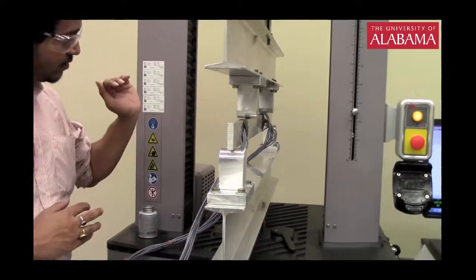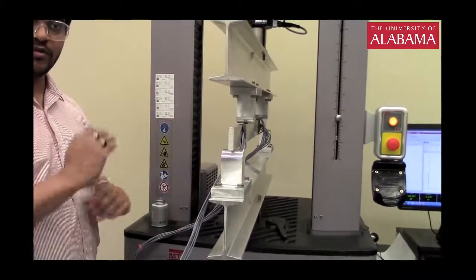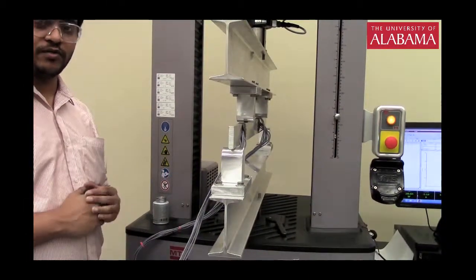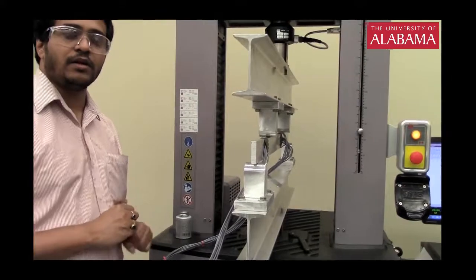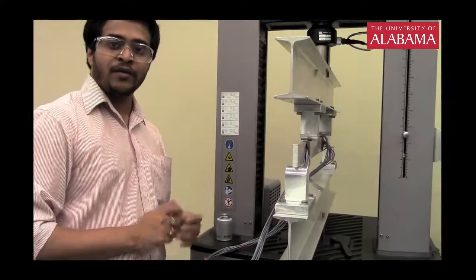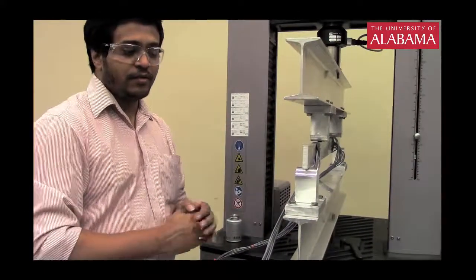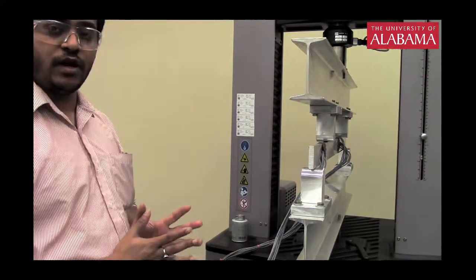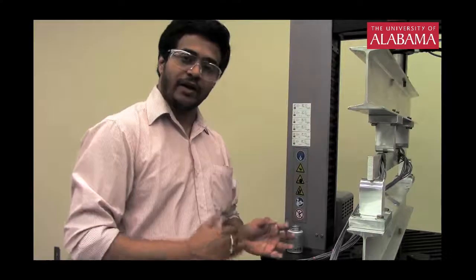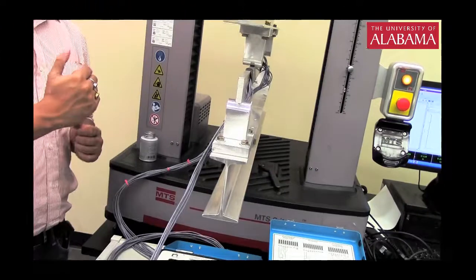Now as far as the 5th gauge is concerned, the way this beam has been set up, and you can see the cross sectional diagram in your manual as well, the 5th gauge has been placed in the neutral axis. So ideally the 5th gauge should be 0. Since we do not have a readout of the 5th gauge as of now, just consider the 5th gauge readings to be 0, because it has been placed at the neutral axis. So we will consider the ideal case that the 5th gauge is at the neutral axis, so that will be 0.